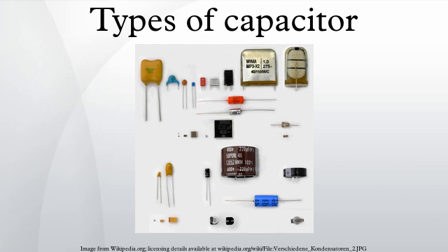Higher pulse rise times are permitted for pulse voltage lower than the rated voltage. Examples for calculations of individual pulse loads are given by many manufacturers, for example WIMA and Comet.